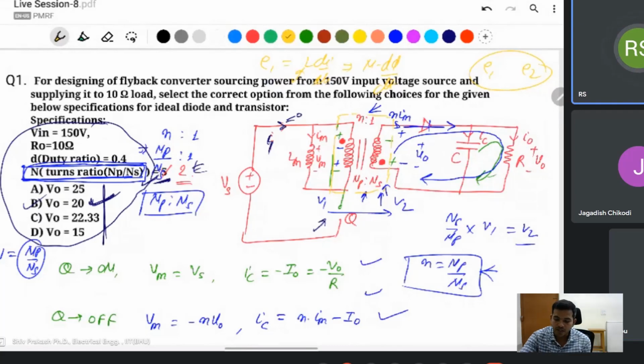We count only the leakage and magnetizing inductance. So this is not an inductance; it is just a winding which has EMF. Those inductances are only represented as the leakage and magnetizing. In the equivalent circuit of a transformer, only these will be present.